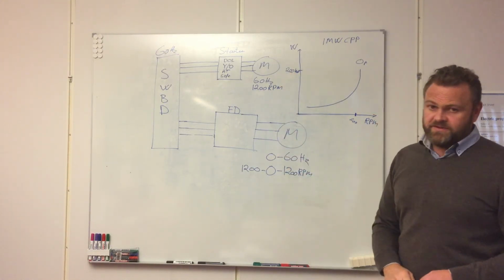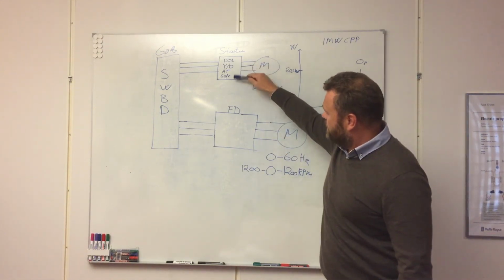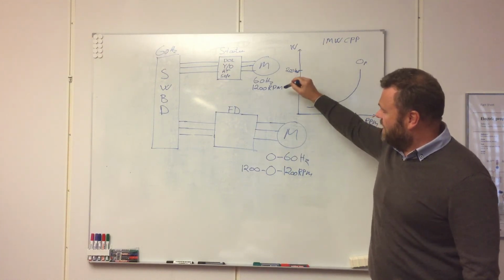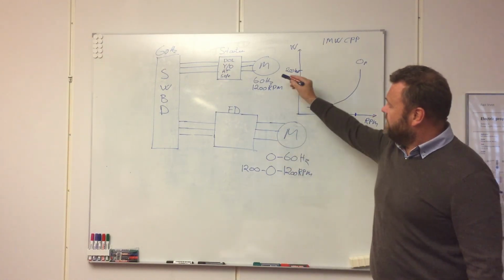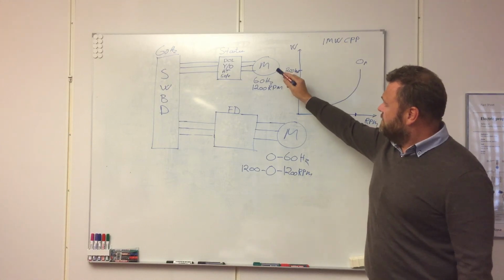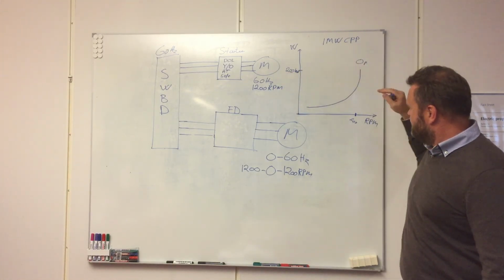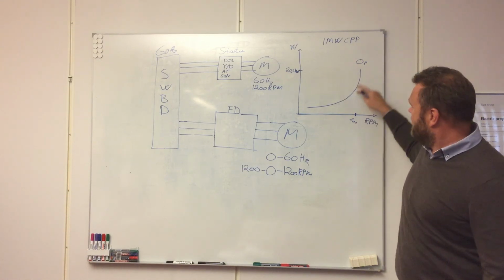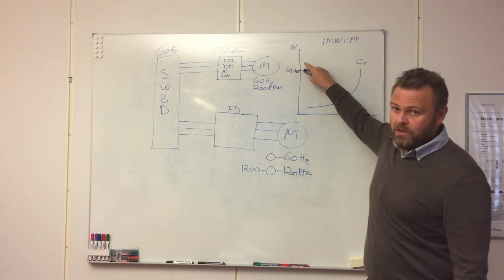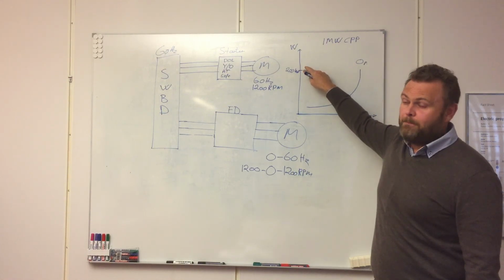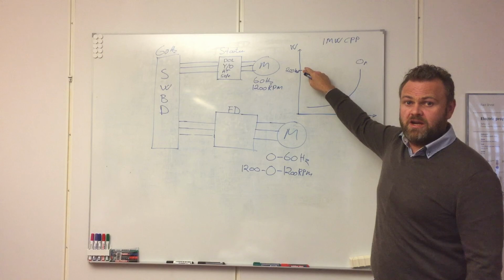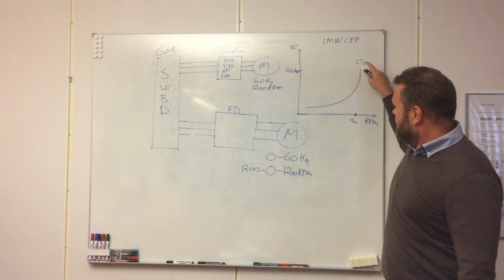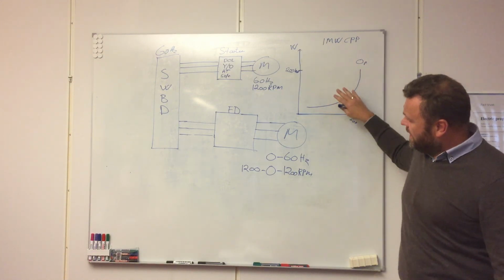Starter, frequency drive, different types of starting methods, still the same. Fixed RPM is the result for this type of starting device, and the result thereafter for the propeller is you have to stick with fixed RPM on the propeller, then you have losses on the propeller side. Maybe it doesn't matter because you use this propeller very little. Maybe it means a lot if you use it a lot, and you should have a look at a frequency drive.